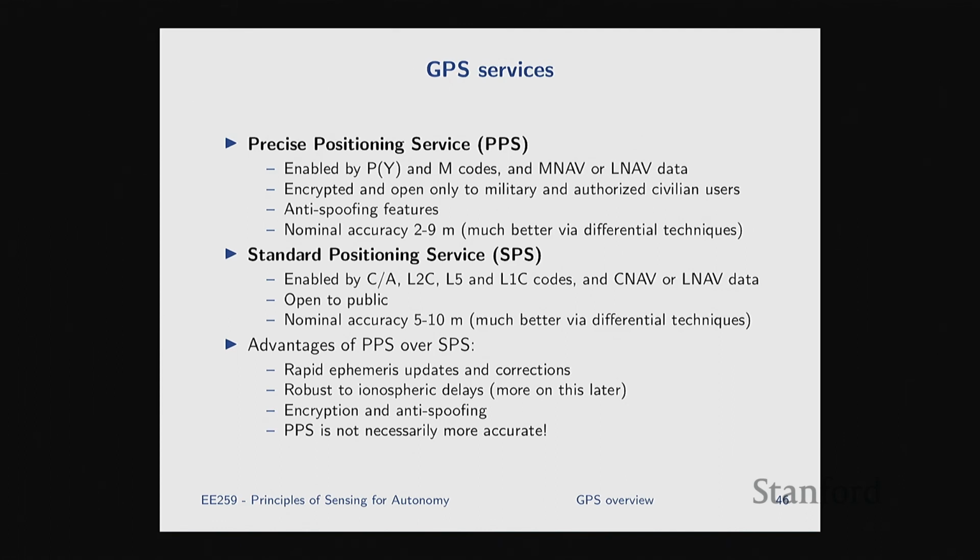Now, regarding the accuracy, whether it's good enough or not really depends on your application, right? Of course, I think we can all agree that GPS is extremely useful, both for human applications and for robotics, but it's not enough. The level of localization accuracy that you get from a GPS receiver roughly positions you globally on a map. You can know you're at roughly this intersection in a city or around some block in a town. But if you were to use only this to fully automate your robot's movement, it's not enough, right? It gives you global, as the name suggests. It works globally. That's the amazing thing about it, and it puts you on the map.